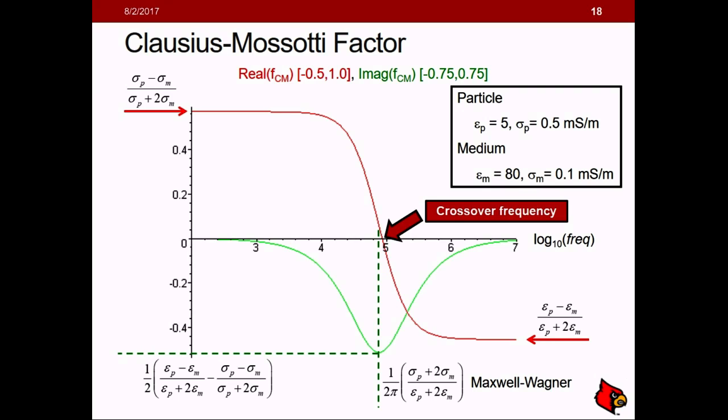So you can tune the conductivity of your system, and maybe you have a system where the crossover frequency of a particle is shown here, and let's say you have a second one. I'll just draw a crude one. Maybe you have another one that does this. So let's say this is particle A and this is particle B, and if you apply a frequency, say here, particle A would experience positive dielectrophoresis and would be attracted towards your electrodes.